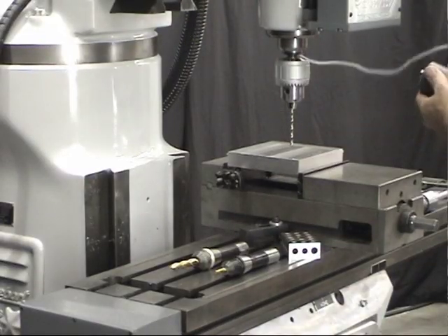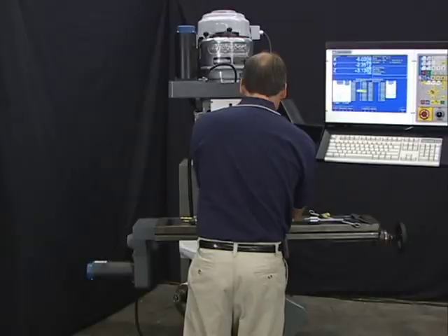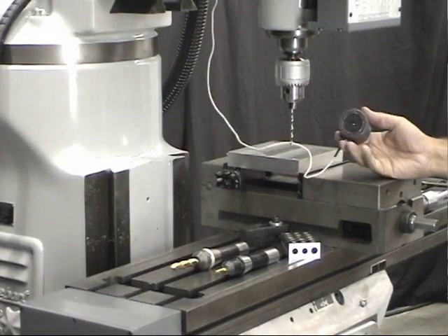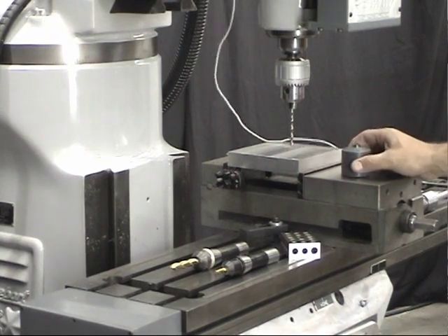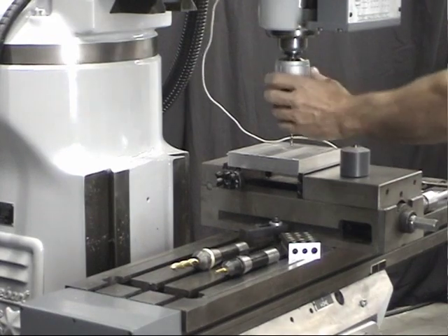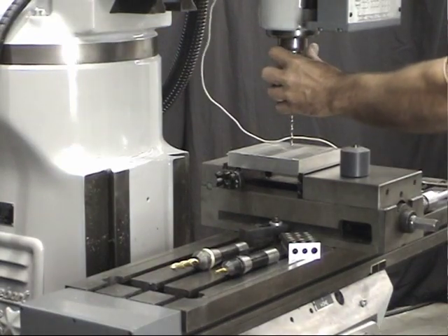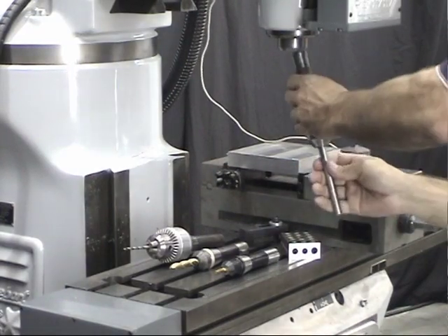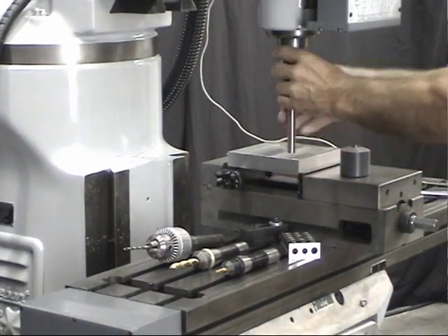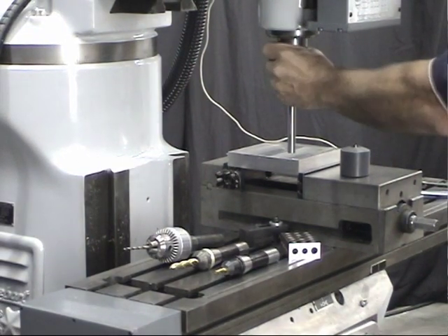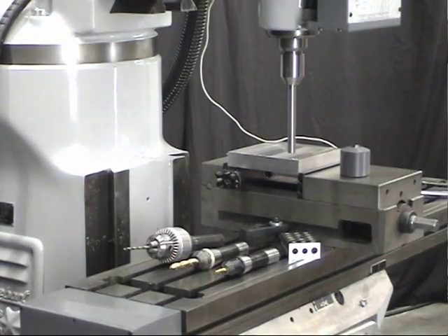I'm going to plug the TT1 in, and again we want to use the top of the vise. There's a nice magnet on the bottom of the TT1, and I'm going to use the top of the vise or the top of the table. Either one works great for a reference position. Now we're going to set a reference position just like we did with the 1, 2, 3 block. So we're going to load the reference tool. Except in this case, the control is going to automatically move the reference tool down to the TT1 and touch off of it. So I'm going to jog on over.